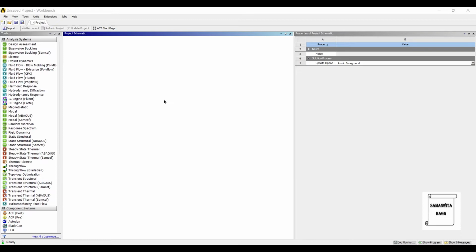The reason is the geometry. If you have observed the previous video, you will understand that the compression spring is more of a slender and long type of spring, whereas a conical spring has a bigger base and a small top, because of which it becomes much more stable when the load is applied on it. We will see the analysis now.